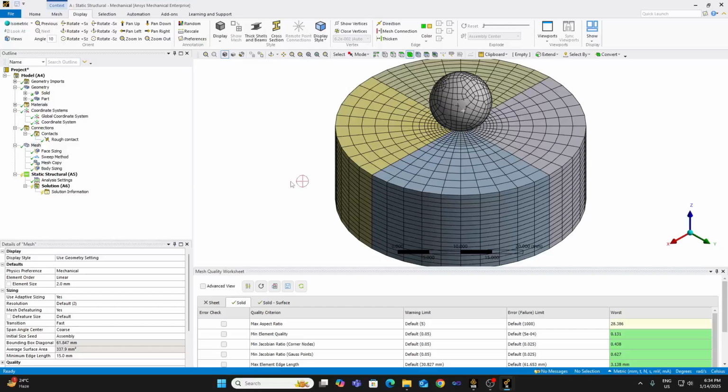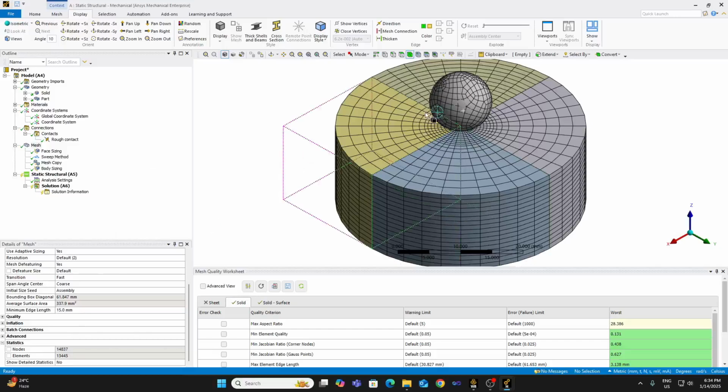Yeah, so with that, what is our node count? About 15,000. If we require, we can at least reduce the element size to half for all the current sizes that we have taken. So one order of mesh refinement is also doable right now. Okay.